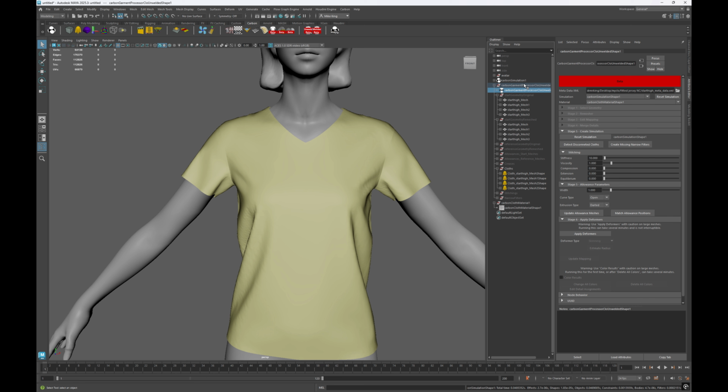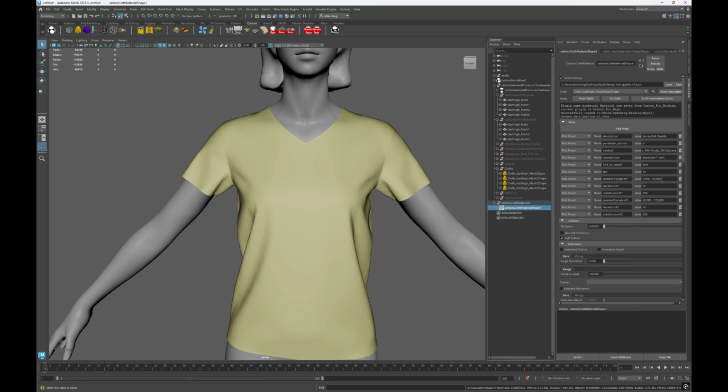Now, in the material itself, it tells you approximately the settings needed for the simulation in order to get a representative material. And so if you've got up to 20,000 triangles, it suggests values of 10 iterations and 100 subdivisions, and 20 to 120,000, 10 iterations and 200 subdivisions.